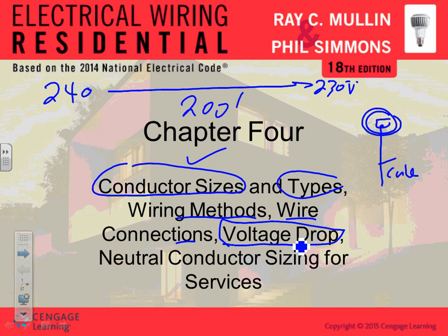Now, the drop that you can do typically in feeders and branch circuits is 5%. So you can drop this voltage down up to 5%, and the equipment's still okay with this. It will function, it will work. We'll talk about this voltage drop in a second.